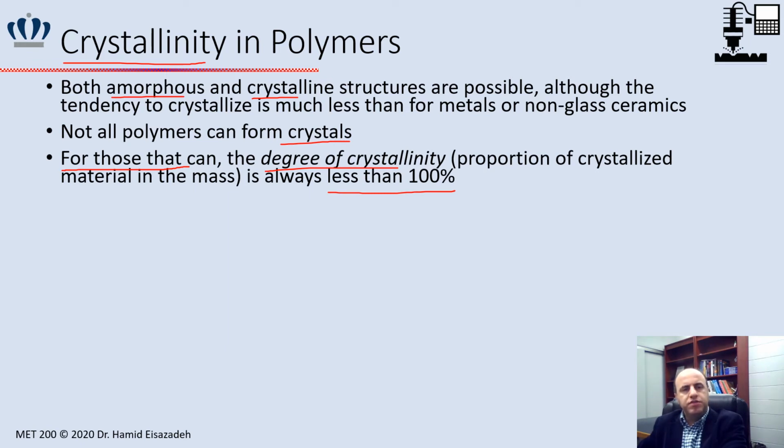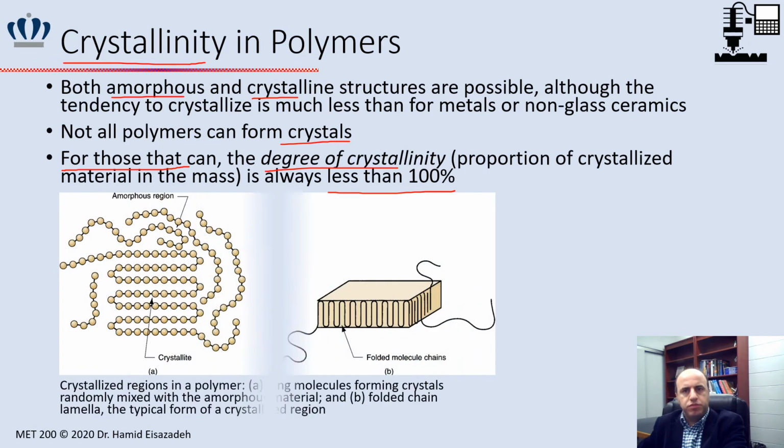In the crystal polymers, we have linear polymers, actually consisting of long molecules, as you see here, with thousands of repeated mers. And crystallization in these polymers involves folding back and forth of the long chain upon themselves.